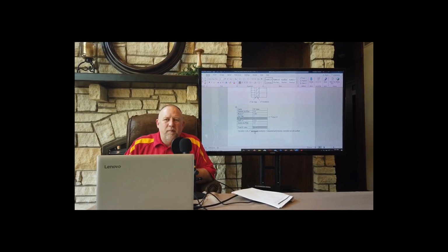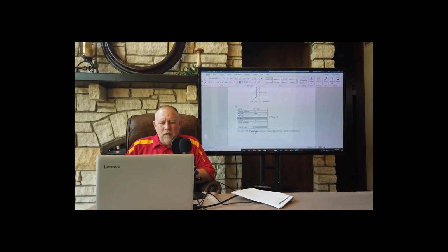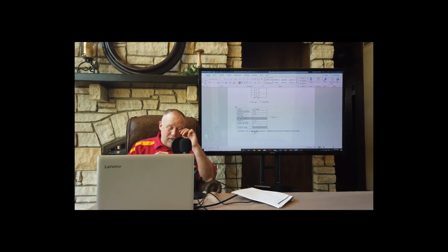Now, let's make a judgment on this R value of 11.45. For a modern building, that would be just barely code minimum. It's not a very good wall in terms of energy efficiency. A better wall assembly would be a total R value of somewhere between 16 and 20. That would start to get a little bit better. A really high performing wall would be over 20. The thing you have to know, though, is once you get above an R value of 20 for a wall, we start getting to the point of diminishing returns.